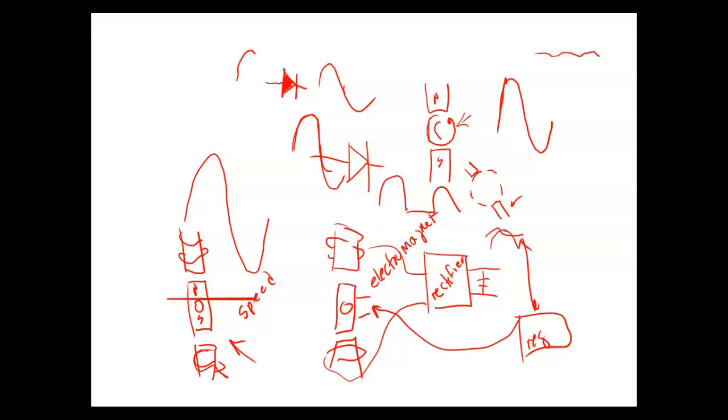But that's not to say you're not going to run into them, because some of you work at plants that have been around for a long time. I learned a long time ago, a manufacturer's not going to change something that's working. If the old way is still working, they're going to use that. Now, new stuff is probably going to use AC tach generators, or optical encoders. The preferred method now with programmable logic controllers is to use an incremental encoder.